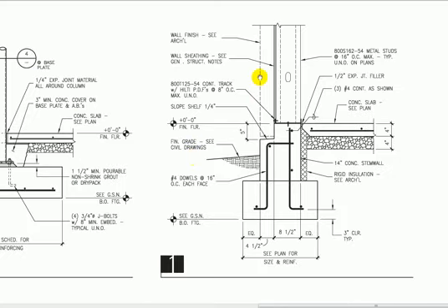Okay, like I said, when we were looking down, this was the outside line and these were the 2 top lines. So what we were looking down, we were cutting through the wall, and we were seeing this little bit of a ledge. The dashed line here indicates that it's the architectural exterior wall, and then here's the indication of the metal studs. 800S162-54 just talks about the size of the stud. It's an 8-inch stud, the 1.62-inch flange on it, and then that has to do with the gauge of the stud. We space them 16-inch on center, unless otherwise noted.